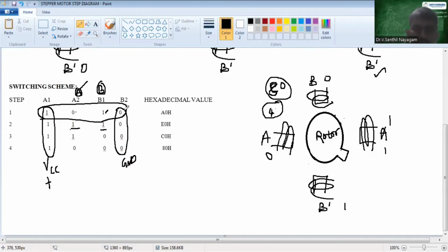Okay. Now at present, I need to mention this with this value. Every row value should be converted to an 8-bit value. So here only a 4-bit value is there. You just add 4 zeros along with this. So this one, 1010, is nothing but A. Along with this, you write 4 zeros, nothing but A0. I have to give 8-bit data to the processor. At present 4-bit data is available, so 8-bit data should be given. That is why I am including 4 zeros on the right side.